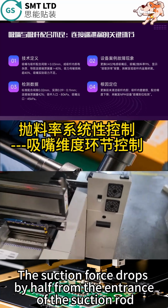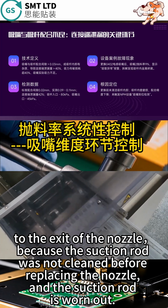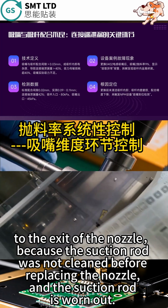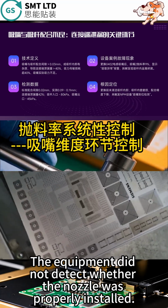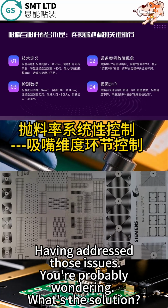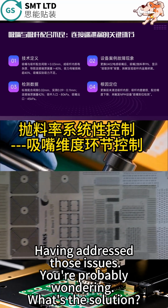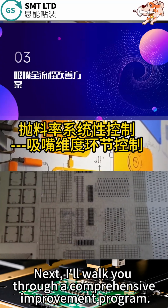The suction force drops by half from the entrance of the suction rod to the exit of the nozzle because the suction rod was not cleaned before replacing the nozzle, and the suction rod is worn out. The equipment did not detect whether the nozzle was properly installed. Having addressed those issues, you're probably wondering what's the solution. Next, I'll walk you through a comprehensive improvement program.